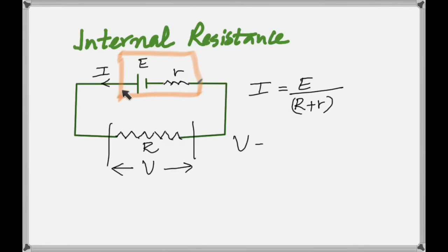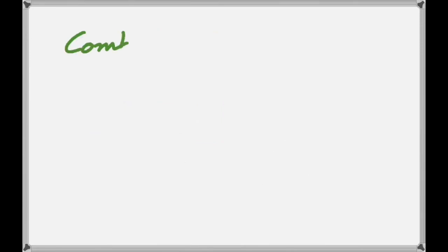Because electrically, this point is the same as this point. And we've talked about this. You don't have anything in between, do you? No. So the terminal voltage is the same. And the terminal voltage is given by this formula. Now, don't be confused. This is the voltage across the load, isn't it? Which I just told you is exactly the voltage across the terminals of the battery. That's one point where students always get confused, so keep that in mind. So you can use that formula to find the internal resistance, okay?